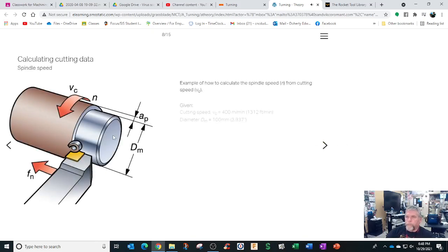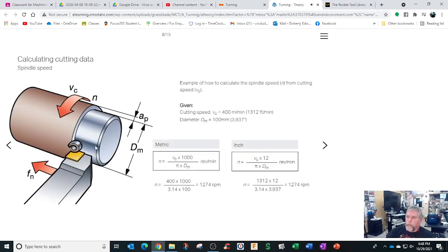Okay, you got your calculating data, but on a lathe, all you need is to have that basic SFM number. Now, I find a lot of times I can't find a quickie chart for that, so I actually end up using the carbide end mill chart to just get me in the ballpark range, because they all have a ton of those on surface feet per minute range for different materials of metal that you cut. A lot of math there.